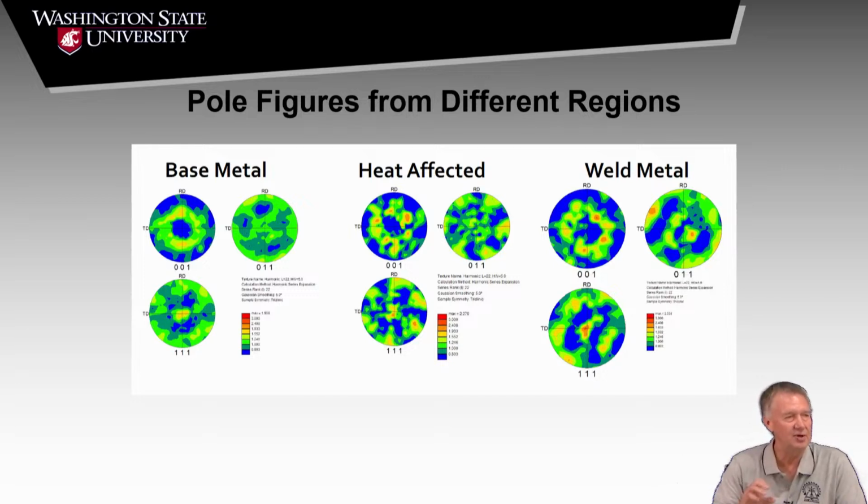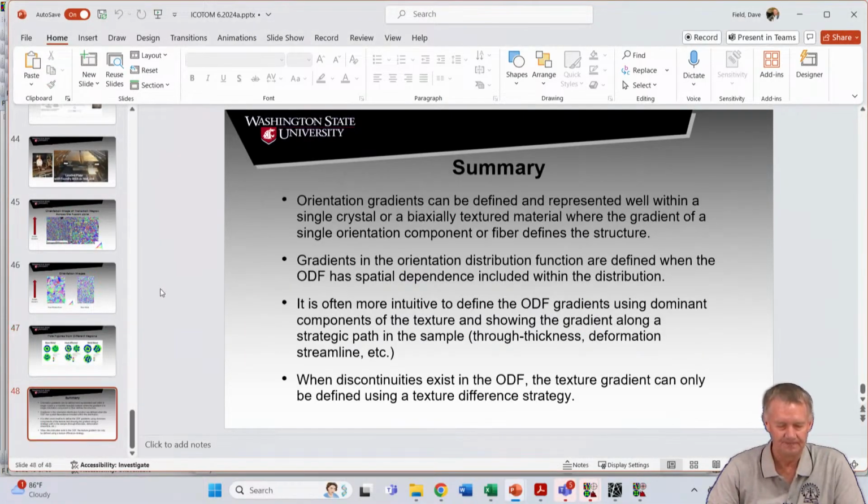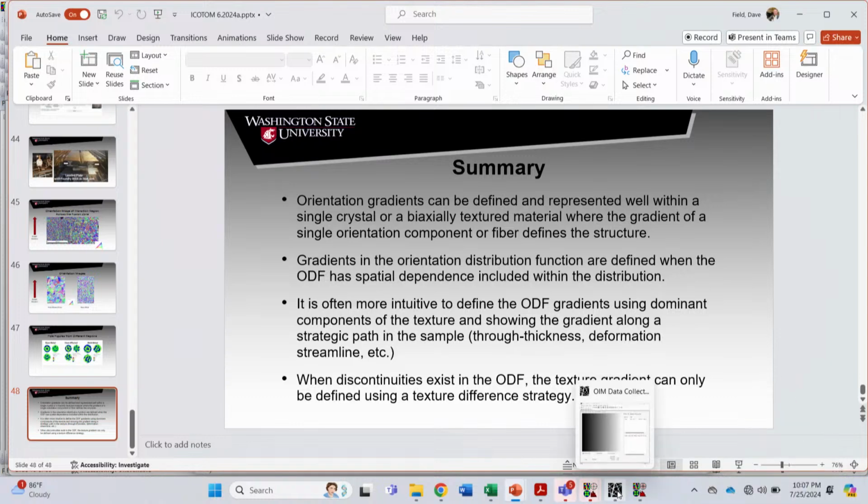And in this case, it was very thick passes. So we're going 3 centimeters of thickness that she's doing the wire arc additive on, and doing it in only 3 passes. So she's filling up a centimeter in each pass. So pretty significant filling. Anyway, kind of boring texture, but a cool project.